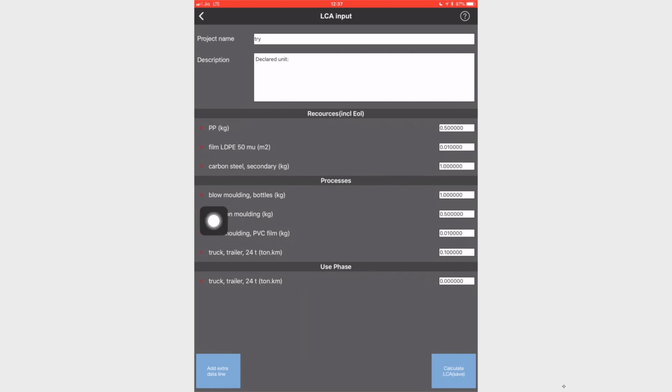There are thickness related limitations. PET can produce very thin bottles, whereas with polyethylene or polypropylene the wall cross section of the bottle is way higher. So, you have to be careful, that will be an alternate design, and you should know how much weight that will consider. Once you change the weight of the materials, you will also have to make changes in the transportation.